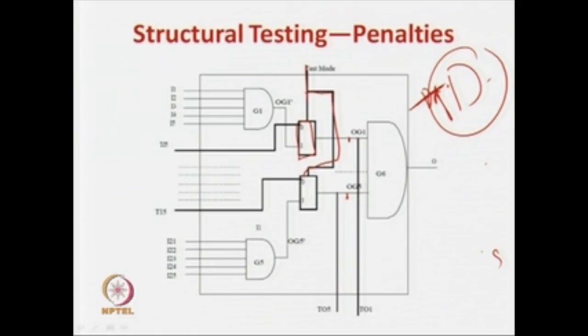So when you say that the test mode is 0, then what happens? Let us say that you apply 1 over here first, in the test mode. So in the test mode if you apply 1, then what happens? The output of the gate, through this 2:1 multiplexer, gets directly connected to this AND gate and the circuit functions normally. So, in this case also if it is 1, this output is connected here and it feeds this AND gate and the circuit is doing a normal operation.